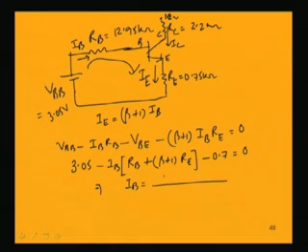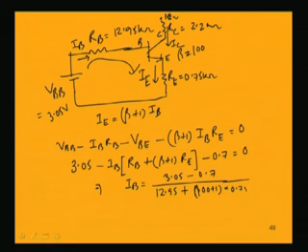IB is equal to (3.05 minus 0.7) divided by RB plus (beta plus 1) RE. RB is nothing but 12.95, plus beta plus 1, where beta is 100 for this transistor, so 100 plus 1 into the RE value 0.75. That gives the IB value to be 0.02651 milliampere. So, we now know the value of IB, and we can find the values of IC and IE.